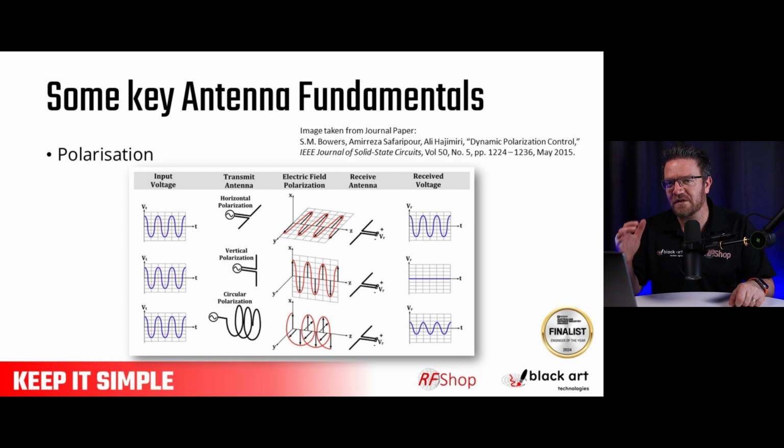The other one is polarization. The focus that I have here is very much on outside the antenna. Of course, you set it up with the antenna, so the antenna needs to launch into a certain polarization. If you look at TV antennas, going back to consumer experiences, there's vertical, there's horizontal, different areas in Australia, in the world where you go, you would see antennas standing differently. That's the polarization. Circular polarization is a little surprise factor that gets used more in the mining and tunneling industry, underground industry. Let me show you why.